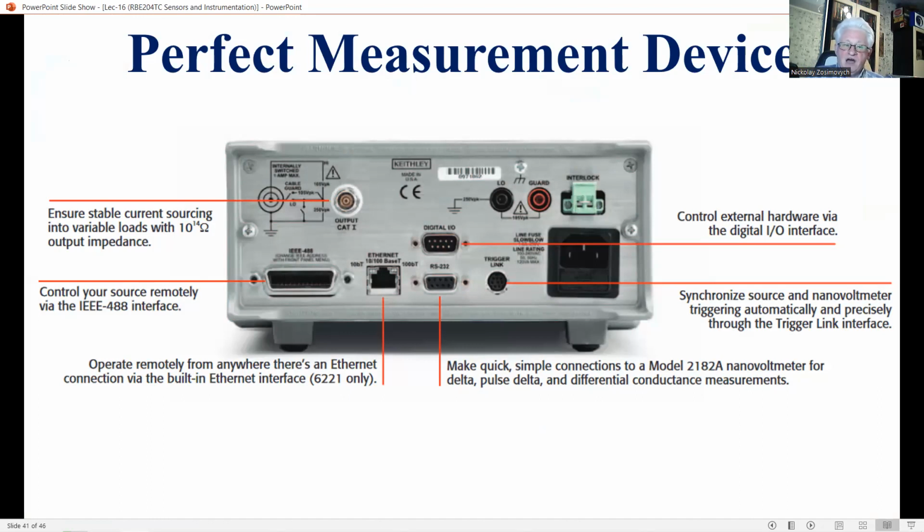First, the output of the measuring device instantly reaches the measured value, a fast response with zero error. Second, the transducer output is sufficiently large. Third, the device output remains at the measured value, with zero error, without drifting or getting affected by environmental effects.